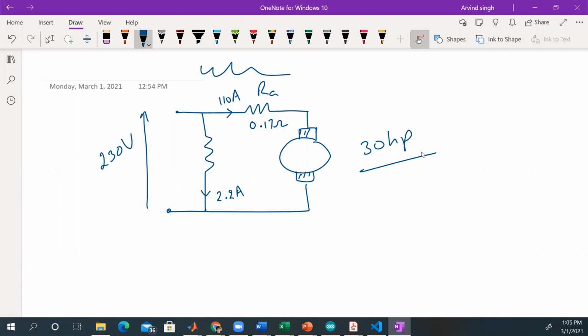So this is different, if you remember, from when we talked about the transformers, because the transformer was a through device. It was just converting power from one side to the next. And there was this confusion about, when they specify the power, which side it is on, because usually they say the rated power, you could get it from any side. So it's supposed to be the same on both sides, but there was that shunt branch in the middle that was taking away some of the power. So it wasn't clear whether it should be input or output, right? But under normal circumstances and the full load, they're pretty much the same. So it was a good approximation, right?